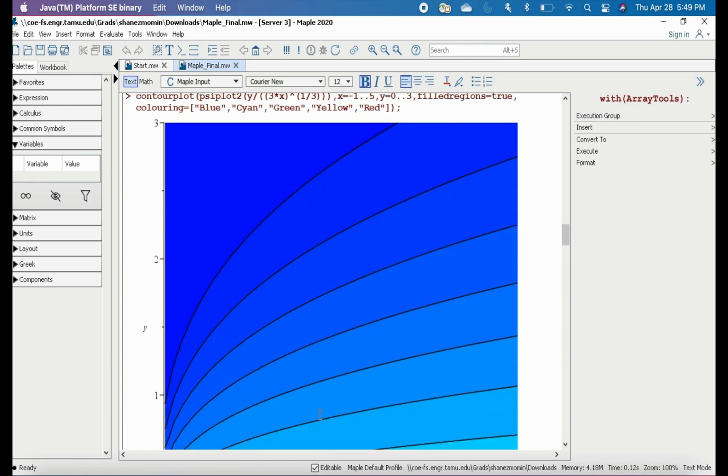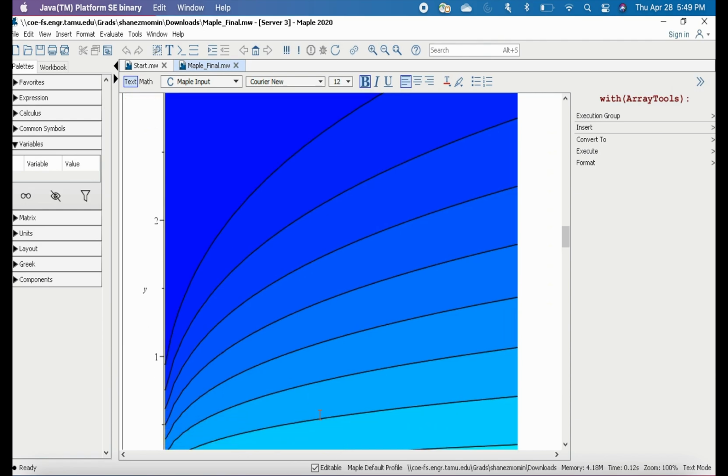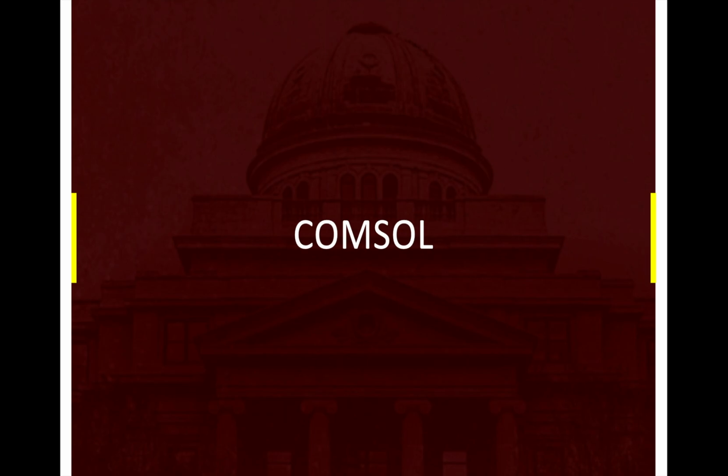We also made a preliminary contour plot for substrate concentration to understand the profile under laminar flow. From the plot, we infer that we will see a waning concentration profile of substrate in the y direction. We will look at it further in our COMSOL simulation. On to our COMSOL file.